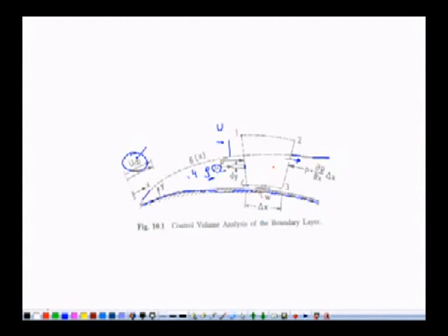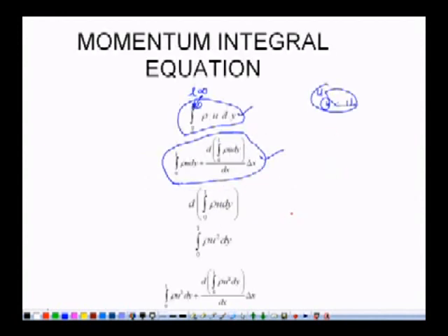And since the flow is a steady flow, it means that inside the control volume, the rate of change of density or rate of change of mass must be 0. So whatever mass is going outside the control volume through face 2, 3 must be coming from 1, 4 and 1, 2. Right. With the help of this concept, we can write the continuity equation.